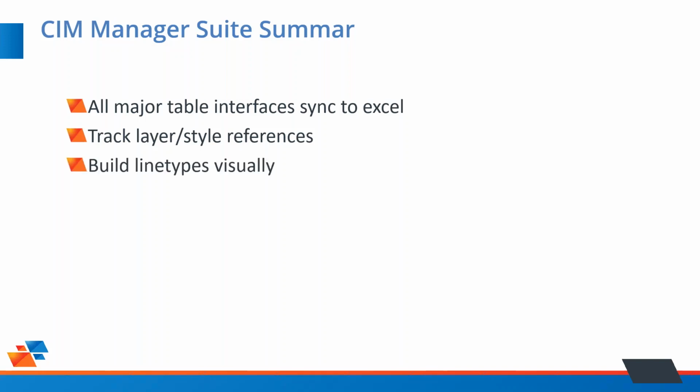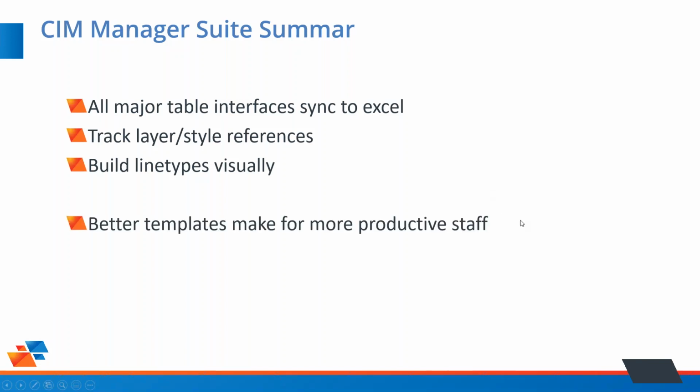Line type editing, we can do this stuff visually. I see a lot of companies that will build custom line types per project. I've seen some people doing right-of-way distances built into the line type. A lot of creative ways to do it. And now it's actually worth exploring because line type editing and creation isn't such a difficult thing. Almost any user can jump in there and do it. In fact, like I said, that's one of the free tools, so you can give anyone access to that one.